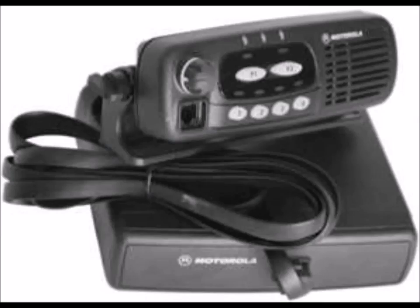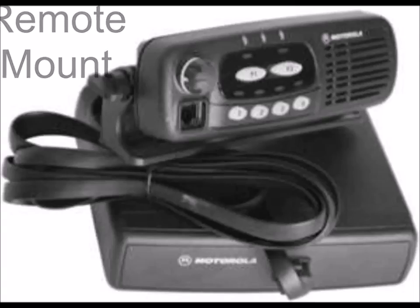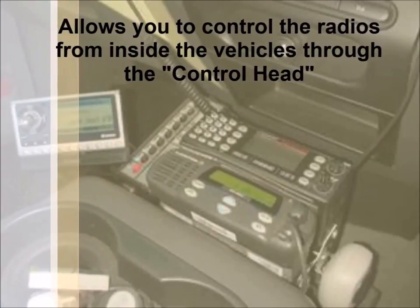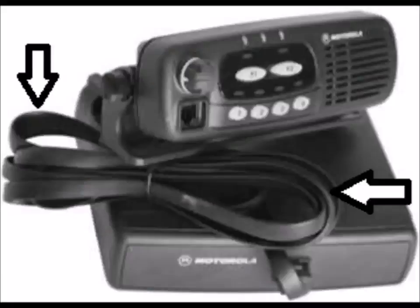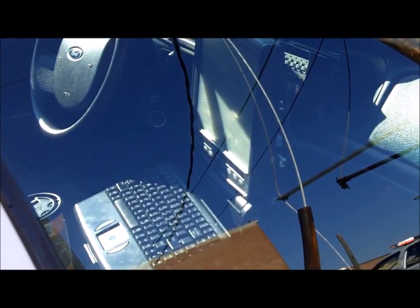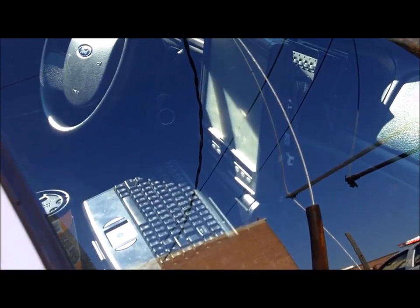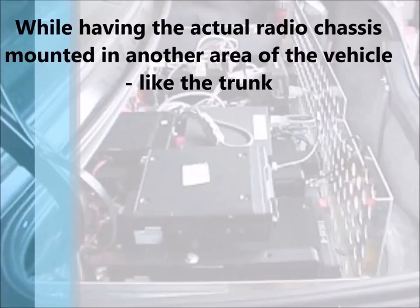Another choice is a remote mount radio. In this configuration, the control head is located near the vehicle operator and the radio chassis is installed elsewhere in the vehicle, usually in a trunk or a radio compartment in a larger vehicle. The control head is connected to the chassis by use of a control cable. Because the control head is relatively small, it can be mounted in tighter spaces, especially when other equipment is installed in the user area. The actual radio chassis can be mounted in other areas of the vehicle, usually the trunk.